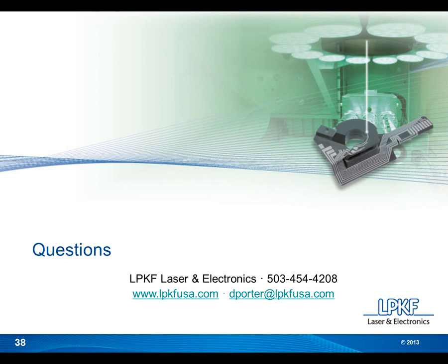The laser spot size is designed as a combination of being most effective in covering a large area and being small for high resolution. Most common systems typically use an 80 micron laser spot. However, we have fine focus options that can be as small as a 25 micron laser beam, so we can make very, very small circuit structures with those lasers, again with very high efficiencies.